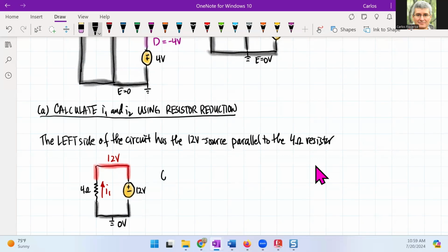So then if I look at Ohm's law, we see that the current is going upstream. So I have to come in and say, okay, I1, what is it? Yes, it's the voltage across the 4 ohm divided by the 4 ohm. But I have to come in by hand and say, yep, this guy is moving upstream.